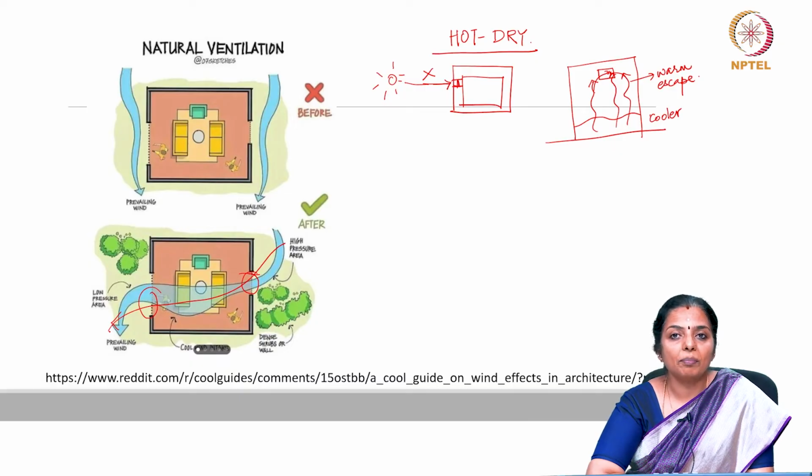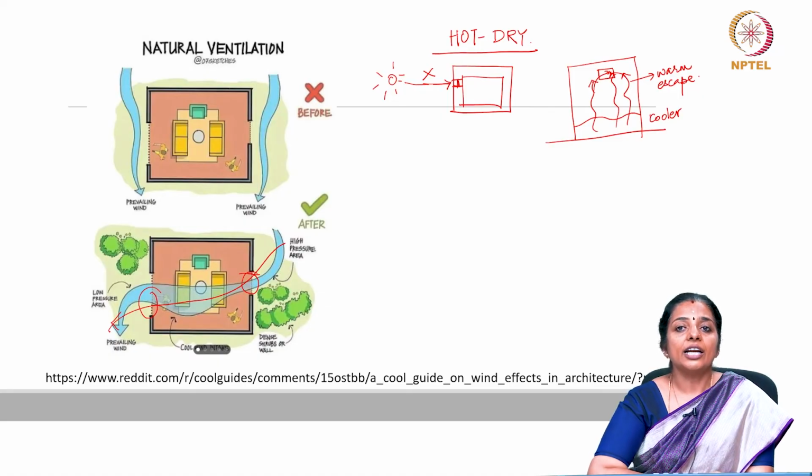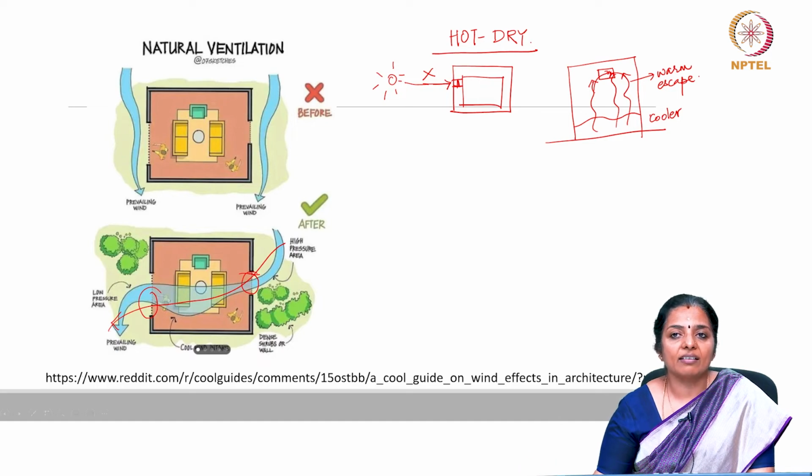Partitions should not be placed near windows, causing an abrupt change of wind direction. Similarly, windows on adjacent walls should preferably not be placed so as to cause an abrupt change of wind direction. It has been said earlier that indoor air speeds are greater if outlets are larger than inlets. It would be desirable to provide every room with a window on at least 1/3 of the wall.